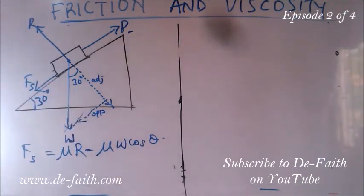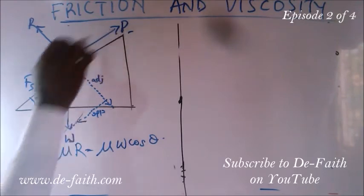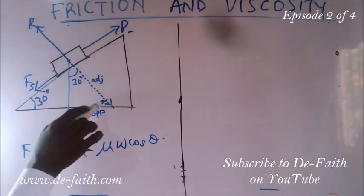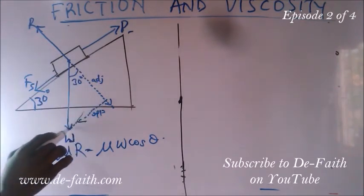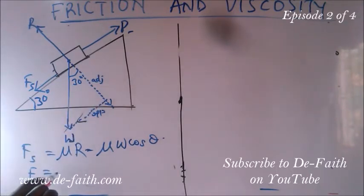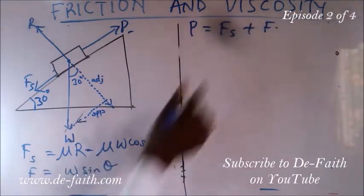Then we are going to resolve a force that will be pulling it up. Let's call that force just F. Now that force is in this direction, and this is the equal and opposite force, which acts in this direction. So that is equal to W sin theta. We're told to calculate the force parallel to the plane that will just move it up. That force will be able to overcome the friction and will be a little bit more such that it will be able to move it up. That force is equal to Fs plus, we'll call it F.